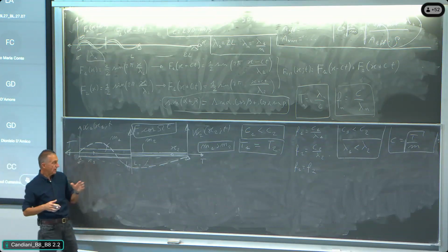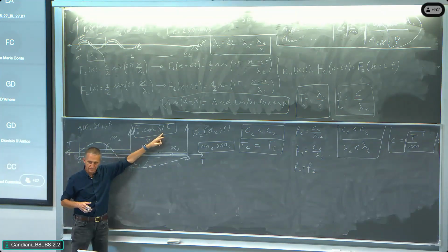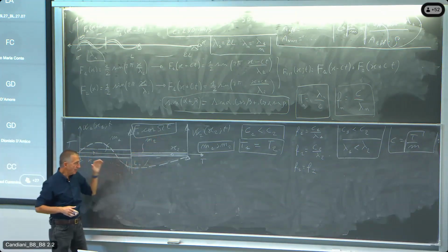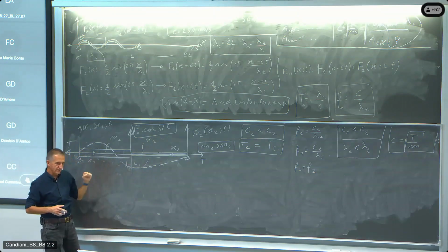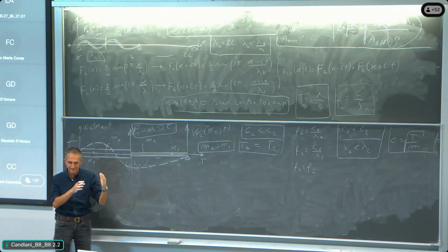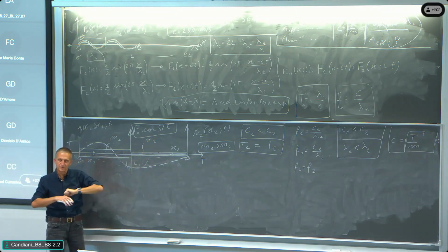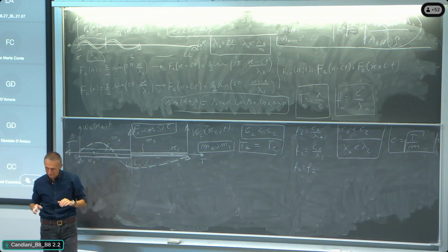But you will recognize that moving this frequency of excitation, approaching one of the natural frequencies, the shape of the vibration will copy exactly the shape of this specific mode of vibration having that frequency. And the amplitudes are jumping up to infinity.